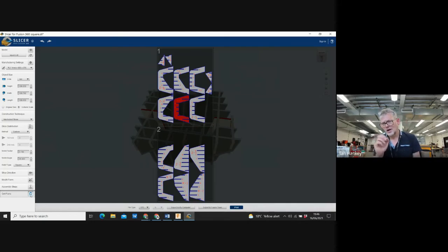The reason why is if we save as DXF, there's a kind of glitch that takes place, and the line that's produced is haphazard. It's made up of many, many lines, and even if you join them all together, it's a kind of scratchy, very long-winded way of making. If you save it as a PDF, we can convert that into a clean DXF, and it's much easier for us to work that way.